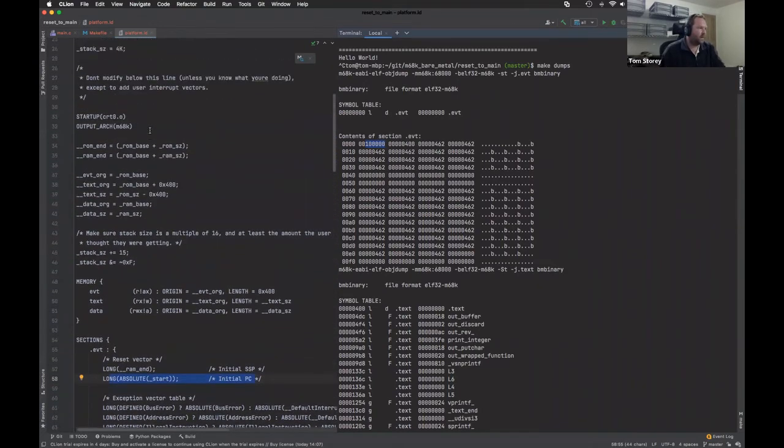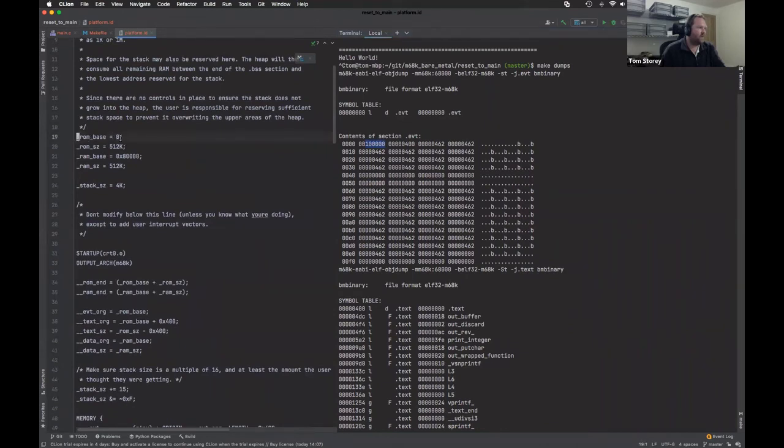I've kind of defined my ROM to essentially be the first ½ megabyte of RAM on my development board, and then the ROM is kind of taking up the second half. So yeah, basically, if you put 512K and 512K together, you get 1 megabyte, and this value here happens to represent 1 megabyte. So when my CPU was to reboot, it would load this value into the supervisor stack pointer, and that would give me the very first sort of stack location.